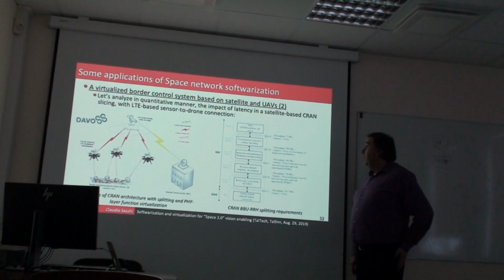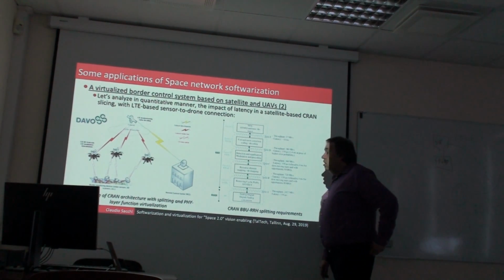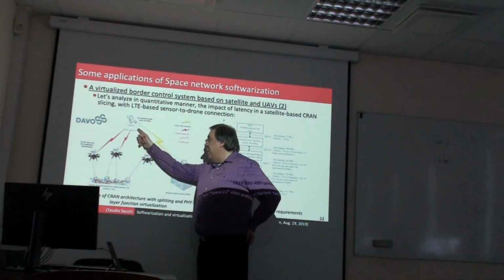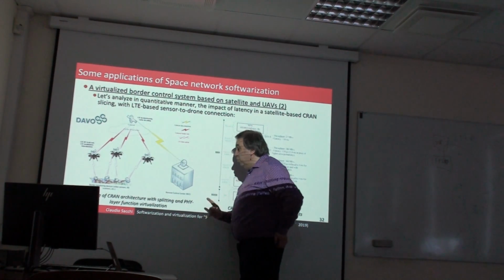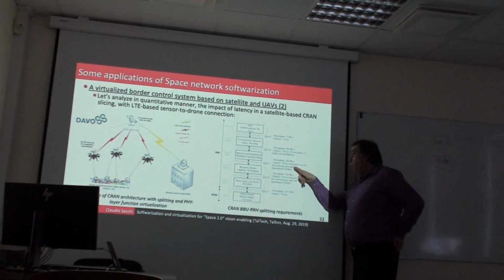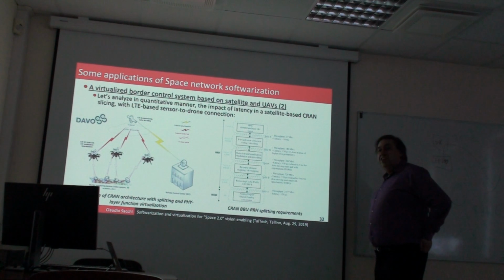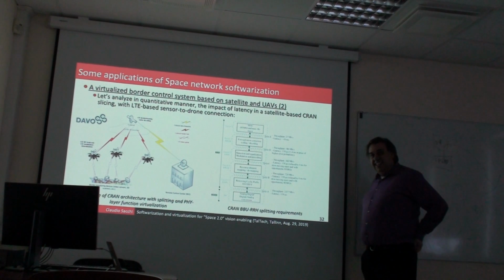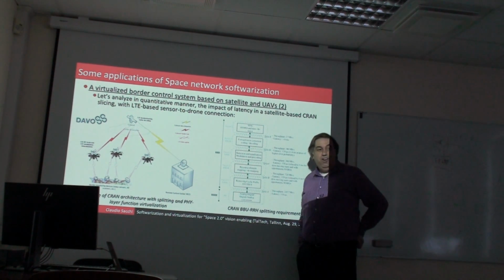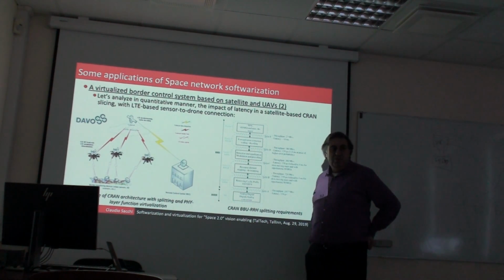Throughput 180 megabit per second, okay. We designed the satellite link, the CubeSat link, in order to cope with this constraint. It's not impossible. It's a bit expensive because we need high gain antennas on the CubeSat. But now in the CubeSat there are prototypical antennas based, for instance, on inflatable antennas developed by the JPL that allow gains of the order of 25, 27 dBi.